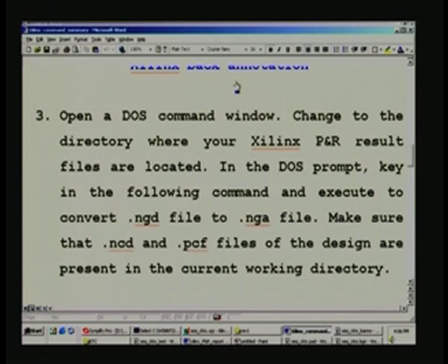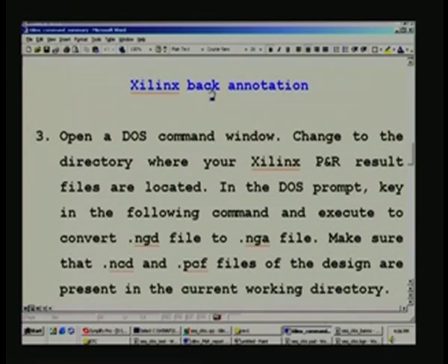We'll start rather the Xilinx back annotation, and the purpose of back annotation is to incorporate the gate delays, and then go on to the simulator and see actually the gate delays shown as a waveform there. In the timing diagram you can see the real delays, and we have already seen in the synthesis tool, in the waveform analysis prior to this, that timing is slightly affected even after optimization. So in place and route it must be more so. I will just read out this one.